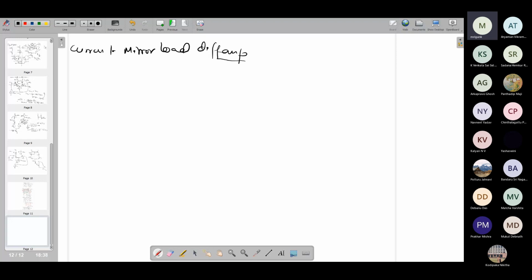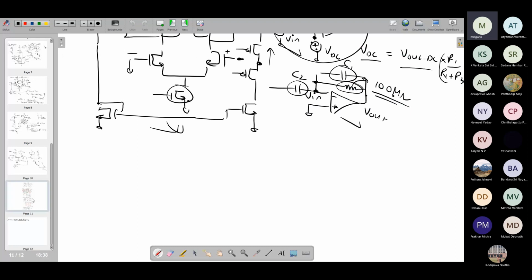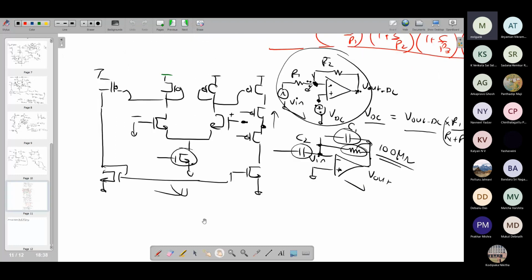The op-amp structure that we just discussed is based on the differential amplifier stage, where the first stage is fully differential. So in the first stage of this op-amp, it was a fully differential amplifier, because ultimately the first stage is differential input, differential output. But overall, if you look at the second stage, it is single-ended. It is folding the signal. It is called signal folding, right?